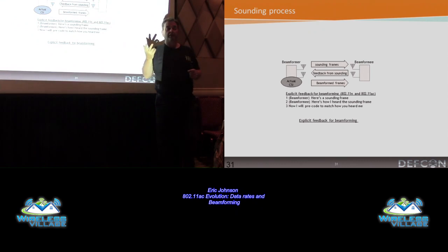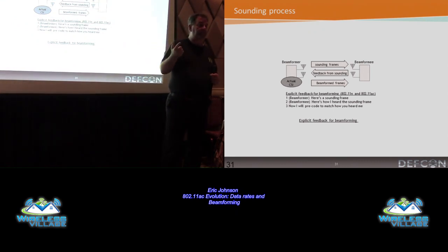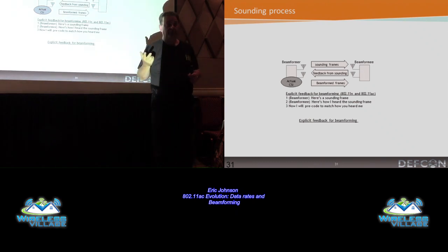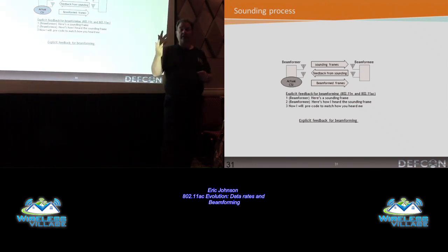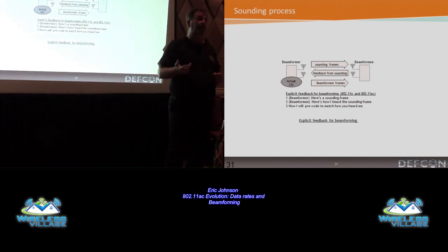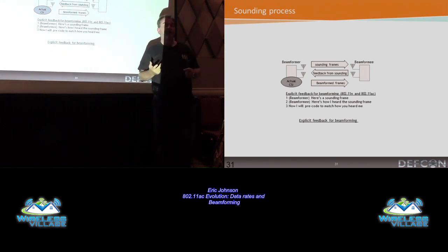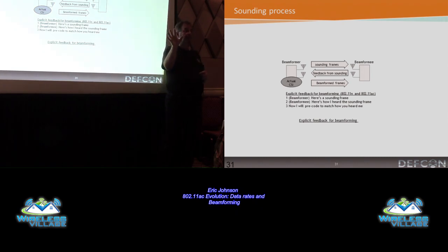There's a couple things going on in the industry right now that are really, really cool. One of them is the Samsung S5, and apparently the new Apple phone, once it comes out with 11AC on it, these devices will support 2 streams on them. So conceivably, that means that you're talking about data rates to a handset upwards of 600 megabits per second of useful TCP throughput. But in order to do that, the beamforming not only has to maximize the signal strength, it also has to maximize the channel to provide multiple streams of data.